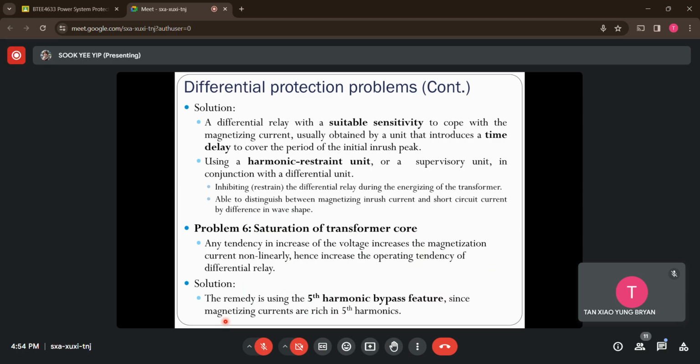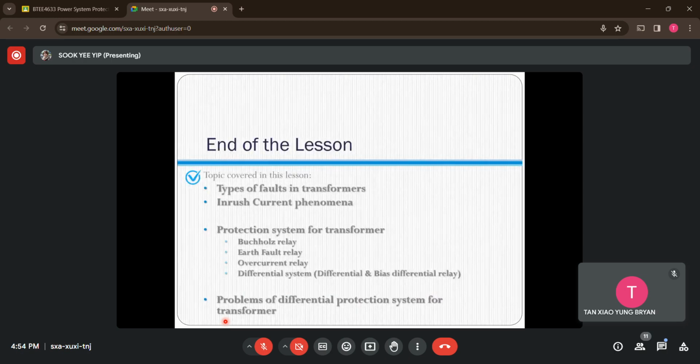All right, so with such, I think we are reaching the end of the chapter, which is a small chapter. We have talked about the protection scheme for the power transformer, talking about different kinds of failures like the internal faults, the tank failures, low voltage or high voltage bushing flashover or short circuit to ground, and core saturation that can cause the wrong operation of the transformer. And then we also talked about the inrush currents, the natural behavior of the transformer, which any protection scheme you implement should not treat as a fault during the time we turn on the transformer.